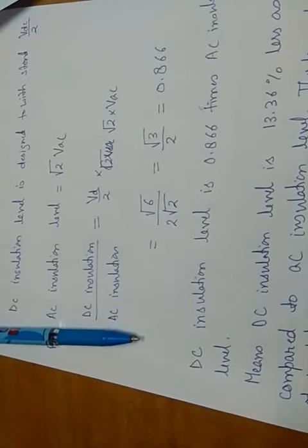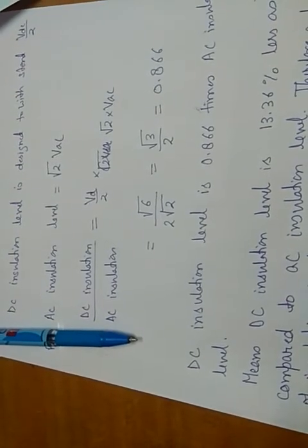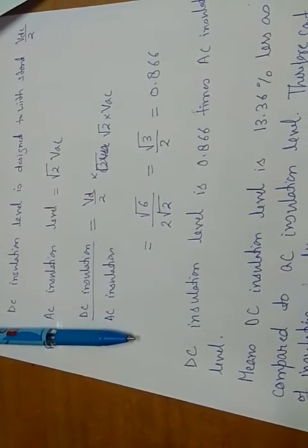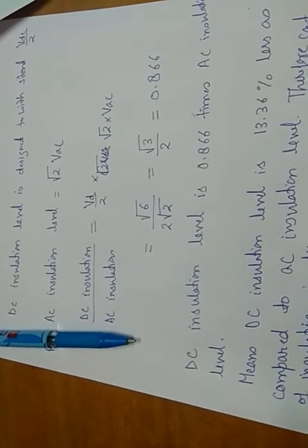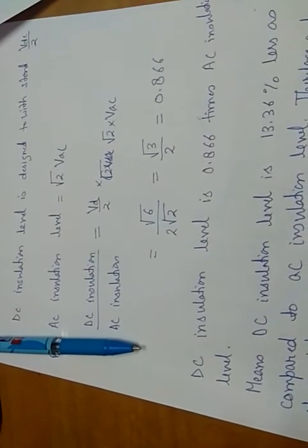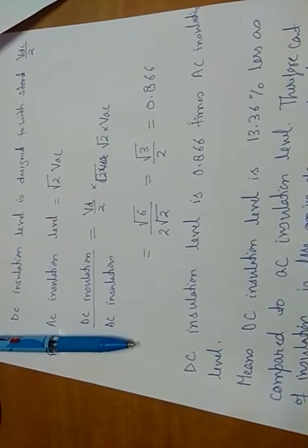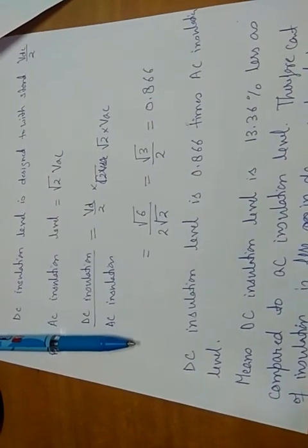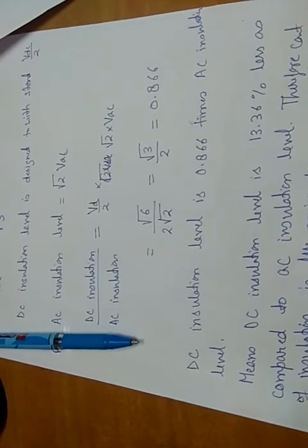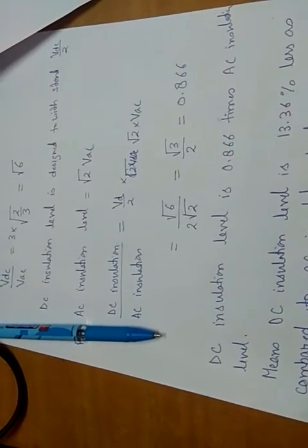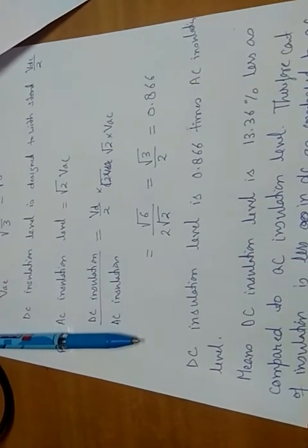That is why power is generated always at 11 kV. If we increase the voltage, we need better insulation in generators, and that increases the insulation cost. So that is why we are generating it at 11 kV.